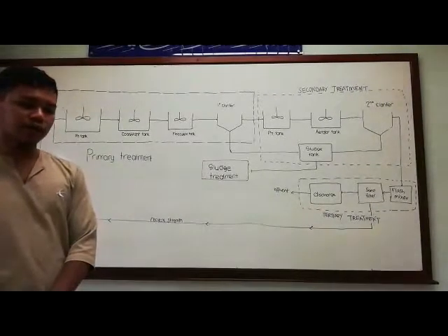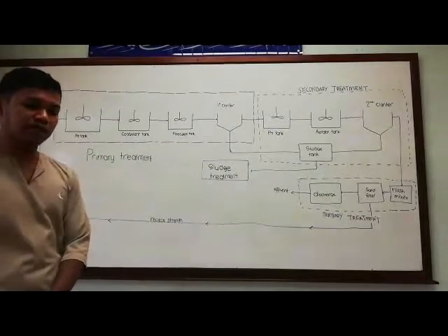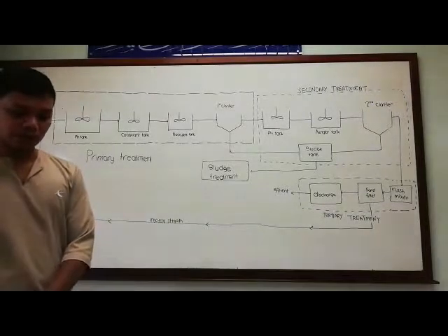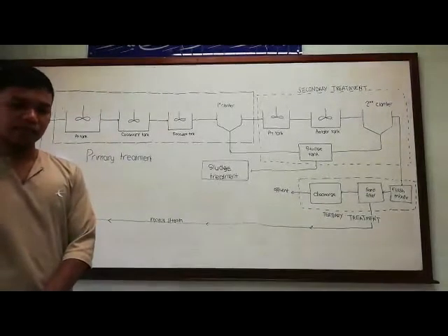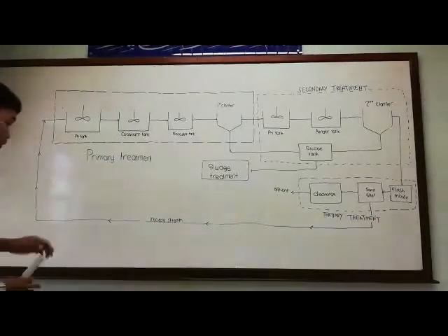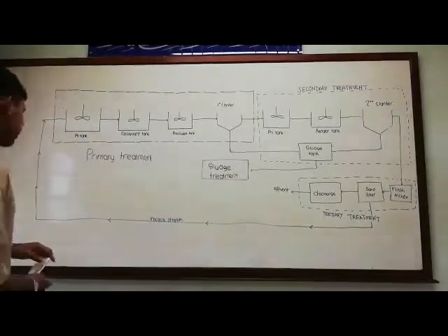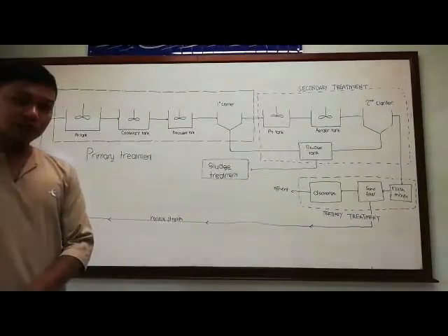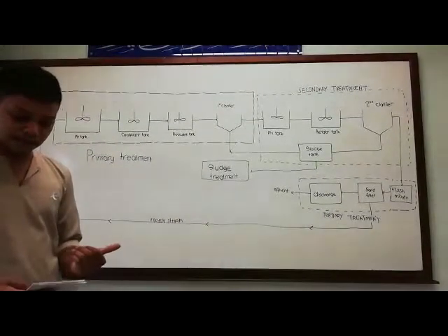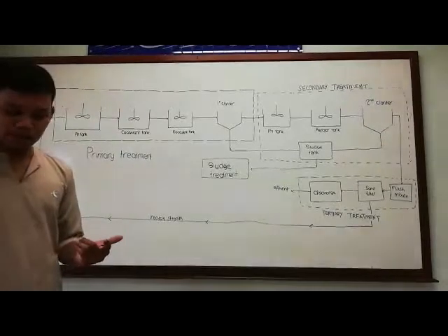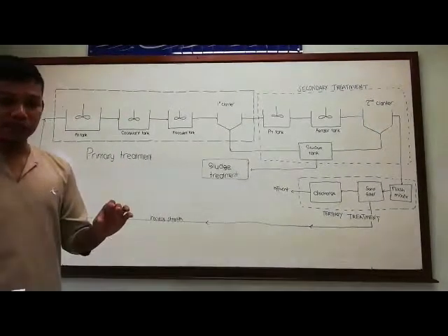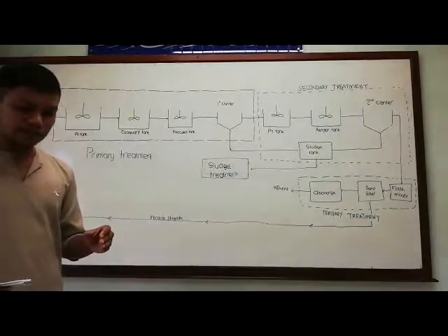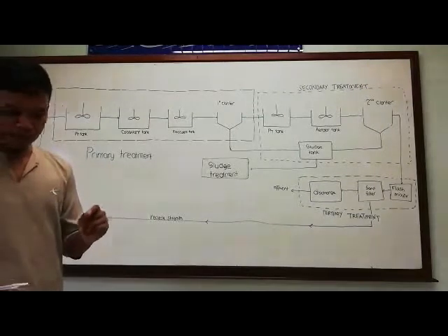Wastewater produced by Maju company usually has a pH range between 3 to 4.5, as stated in the question. So in order to reach a neutral pH, it needs to be treated first in the pH tank. In the pH tank, a chemical base is usually added, with the purpose of removing dissolved solids and increasing the pH of the wastewater itself. This step is also taken to ensure smooth flow for the next section.